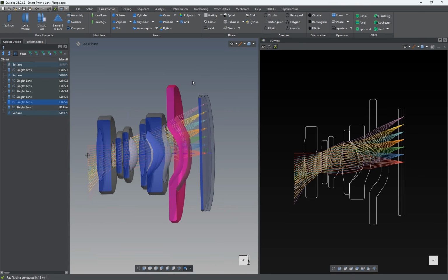Adding chamfers or flanges does not affect the optical surfaces. In summary, by adding chamfers and flanges we are able to design our optical system to reflect how it will look after manufacturing, including the real geometric dimensions of the optical elements. And especially for lens optimization in QUADOA, adding chamfers and flanges has the advantage that edge thicknesses or edge airspaces are taken into account, and this leads to a more realistic optimization result, since the optimization is based on the real physical dimensions of the optical system, including the geometries outside the clear aperture.